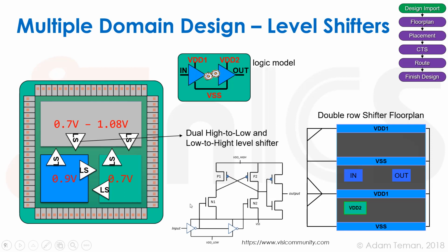These types of gates have one main voltage, the VDD high, which would usually in this case be VDD2. The inverters at the input may work on the low VDD, so they might need a second VDD. But we're going to have to stick this into these standard cell rows, and often these will be a double row or triple row, as we can see here, and that's okay.